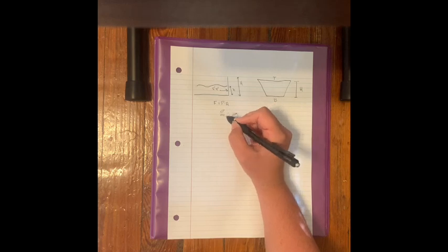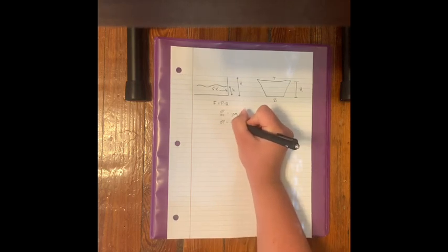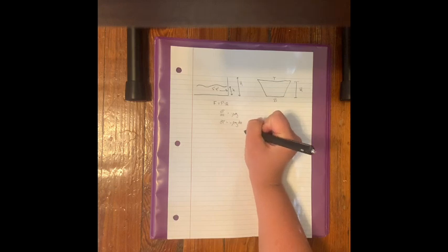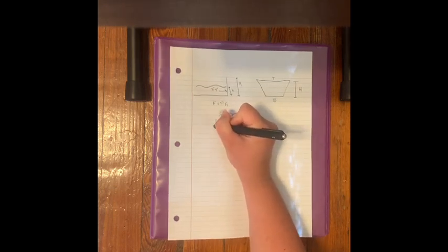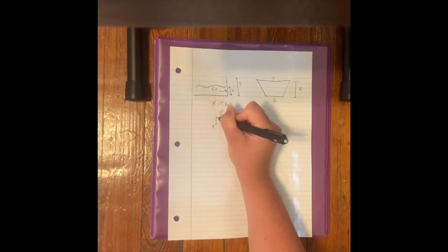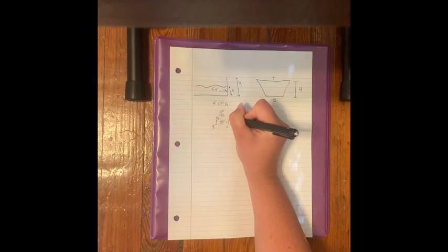So first we are going to start by simplifying this to say dP, our change in pressure, is equal to the negative density times acceleration due to gravity multiplied by the change in height. And we'll integrate both sides, and our pressure one will be from pressure 1 to pressure 2 to a location Z1, Z2.